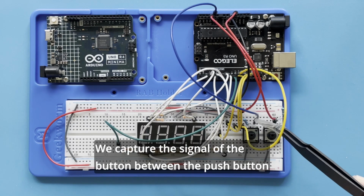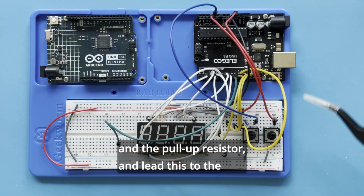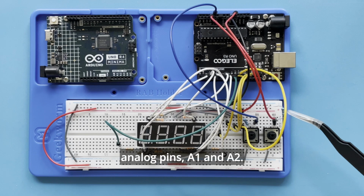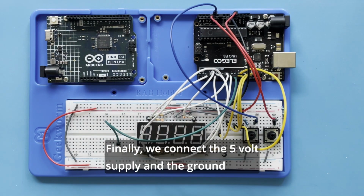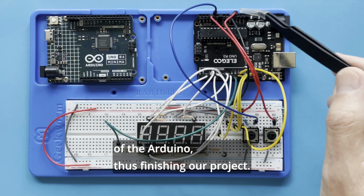We capture the signal of the button between the push button and the pull-up resistor and lead this to the analog pins A1 and A2. Finally, we connect the 5-volt supply and ground of the Arduino, thus finishing our project.